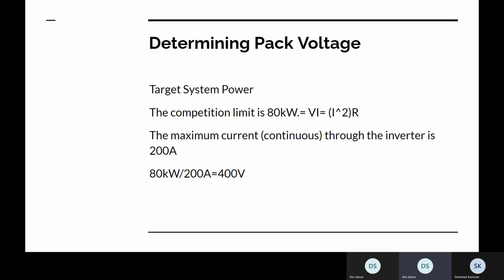You multiply that by what we actually want our voltage to be, which is a 400 volt system, and you get the 8.3 kilowatt hour figure. Yep, it's not 24 by 400, it's 20.75 by 400. That gives you 8.3 kilowatt hours. Gotcha. Thanks for that catch.